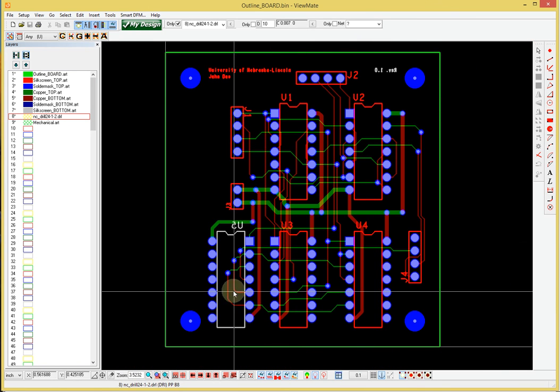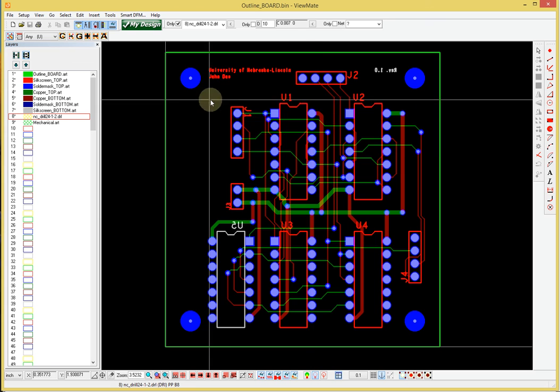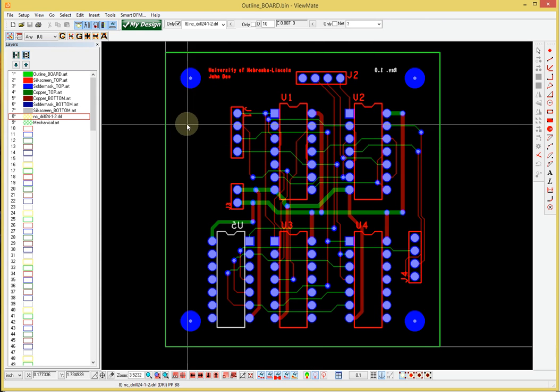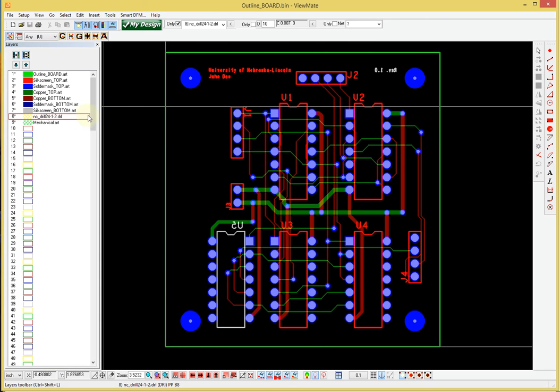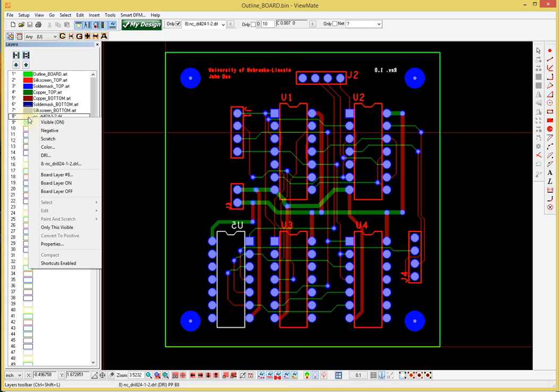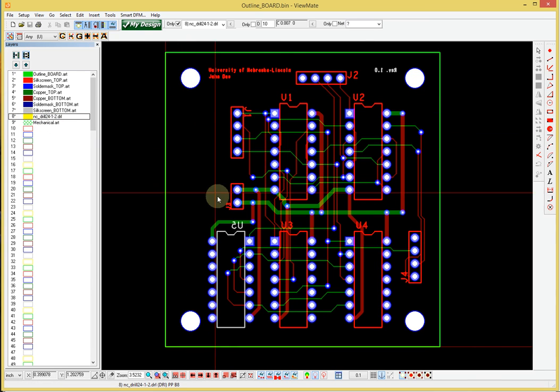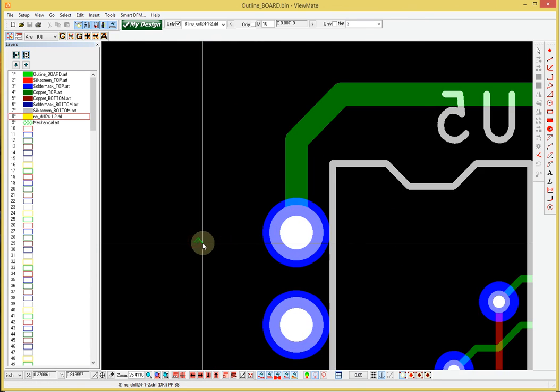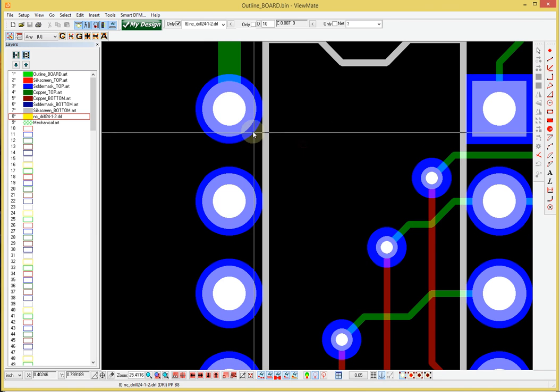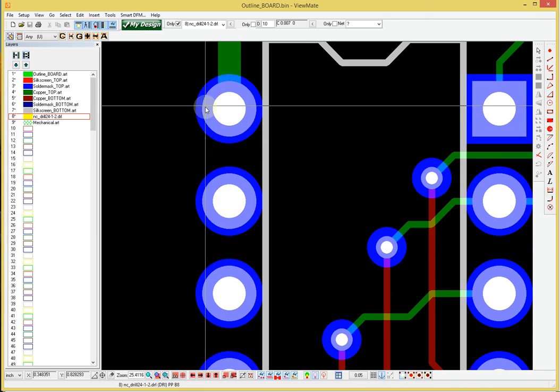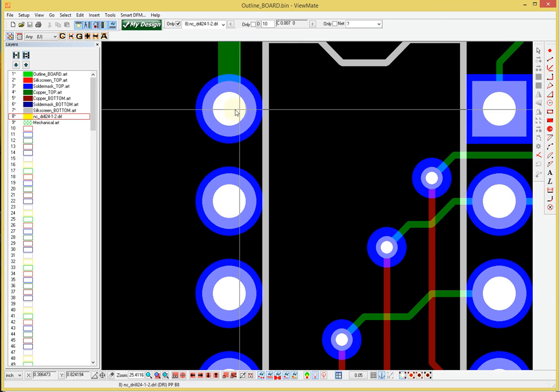After the design is produced, the manufacturer needs to drill holes wherever holes are needed. To do that, we have a separate file called an NC drill file, which shows how the holes are drilled. So for all of the parts, we have pads surrounding the hole. In this image, it's shown in white, so it is drilled through the board itself.